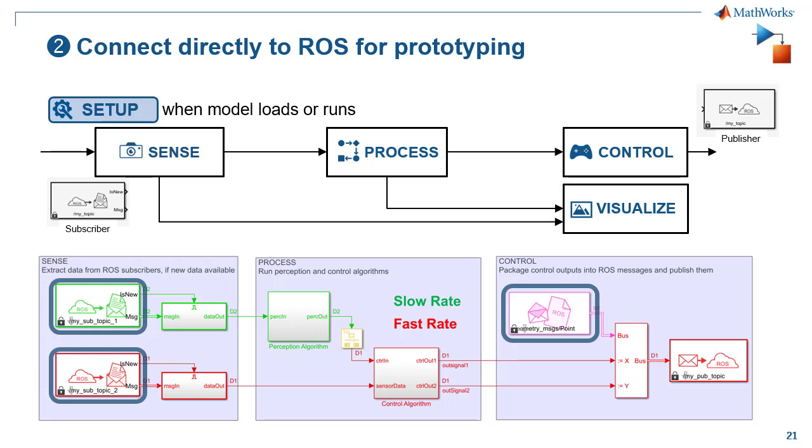One thing to note here, you see these blocks that I highlight which include ROS in them. These are ROS blocks coming from ROS Toolbox to read the data, subscribe to the topic, as well as create a message and publish a ROS topic. These blocks allow you to communicate with ROS without writing any code.